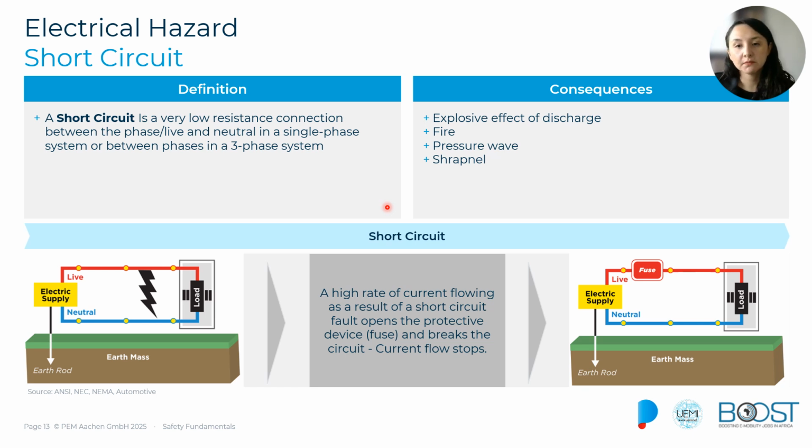And finally, there are external factors that can come in. For instance, if we place a metallic tool on top of one of our connectors, that might create a short circuit. Also, the breeze in general, moisture in the air, and so on. All of that can create direct paths for the current that will produce short circuits.